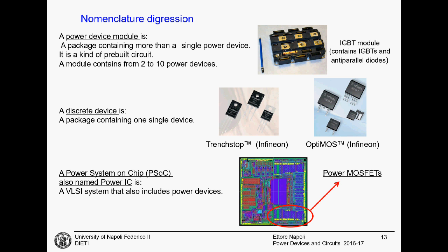It's not like in digital circuits. When you design a full adder once, you can use it in every circuit. If you describe your circuit in good HDL language, porting this circuit to another technology is difficult, but you don't have to start from scratch. The synthesizer, the software, will help you a lot. For power circuits, it's not like that. You have to design more or less everything from scratch.